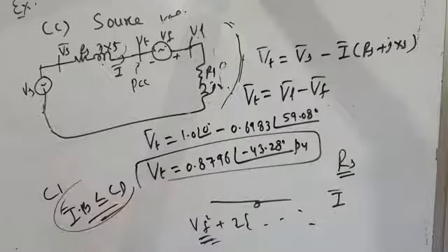This is not the only function that DVR takes care of. It takes care of voltage swells also; there may be an increase in the voltage, and it takes care of that also. It takes care of voltage flickers also. It compensates voltage unbalancing also, and it compensates voltage harmonics also. Some of those aspects we'll study in future lectures.